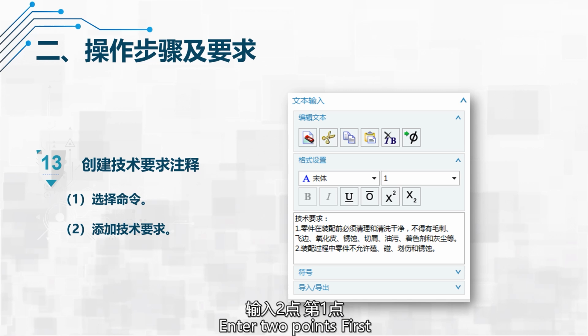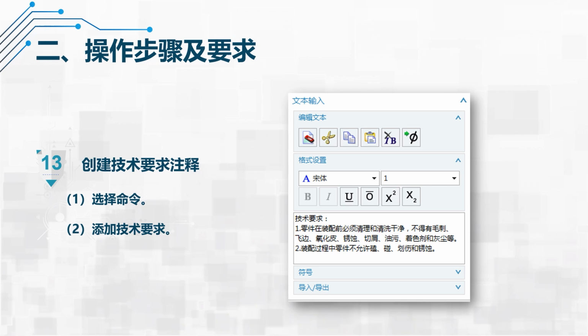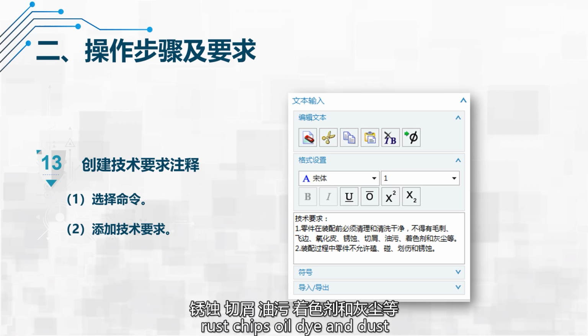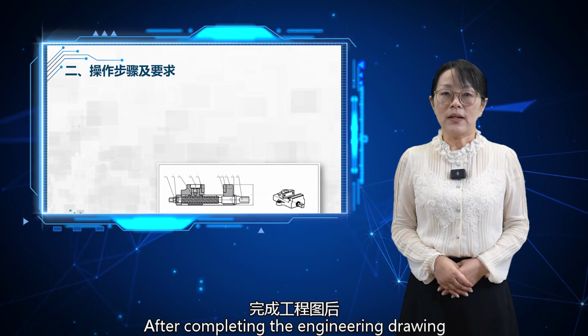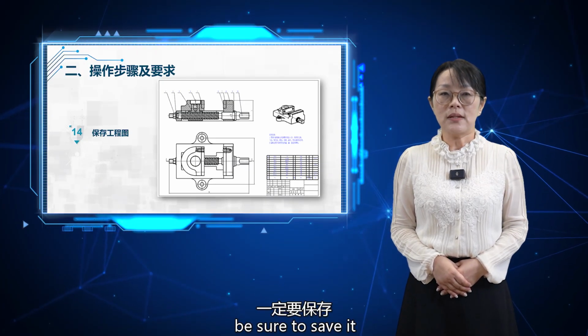Enter 2 points. First, the parts must be cleaned and washed before assembly, free from burrs, flash, oxide scales, rust, chips, oil, dye, and dust. Second, during assembly, parts must not be bumped, scratched, or rusted. After completing the engineering drawing, be sure to save it.